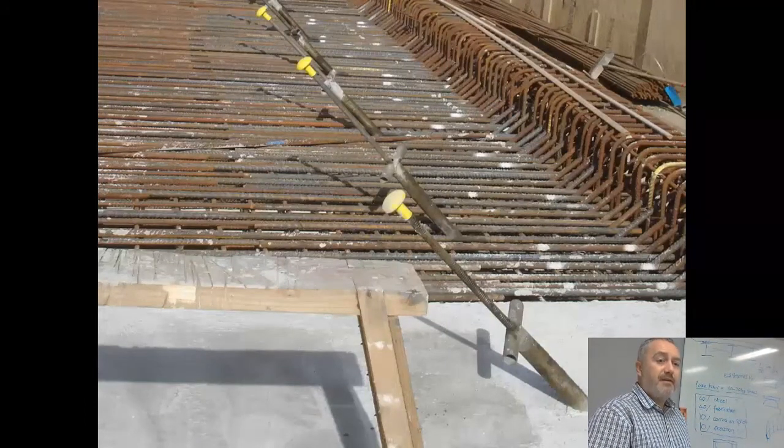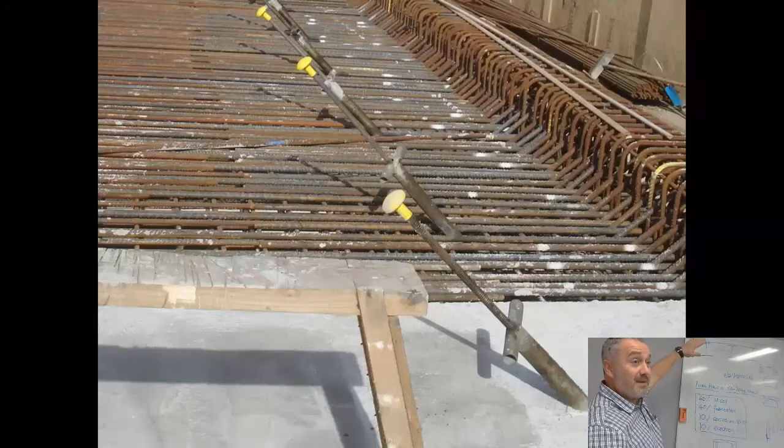You'll find that the consistency of the material, if it's stiff enough, you can pour the concrete. You can put concrete on almost vertical. I think when we cover high-rise concrete frame buildings, I'll be showing you one where they're trying to get concrete on a sort of 15-degree slope, and you'll see how it starts off too sloppy and it all drops off.